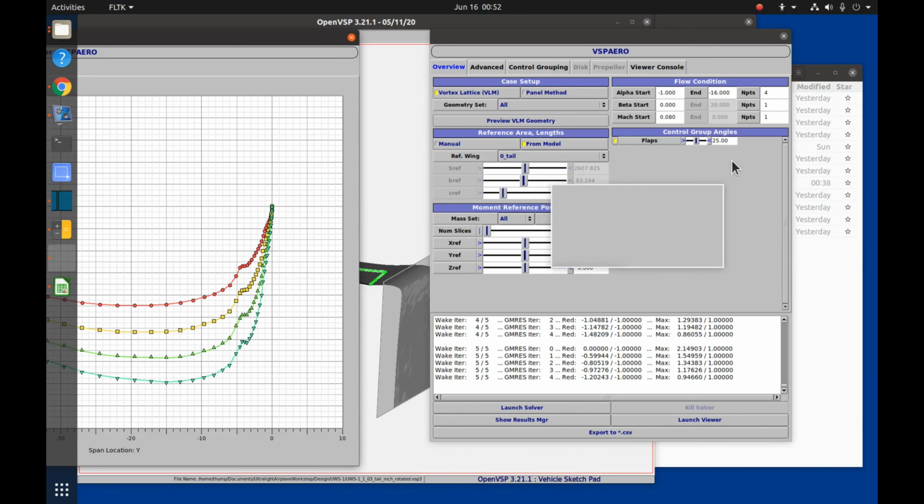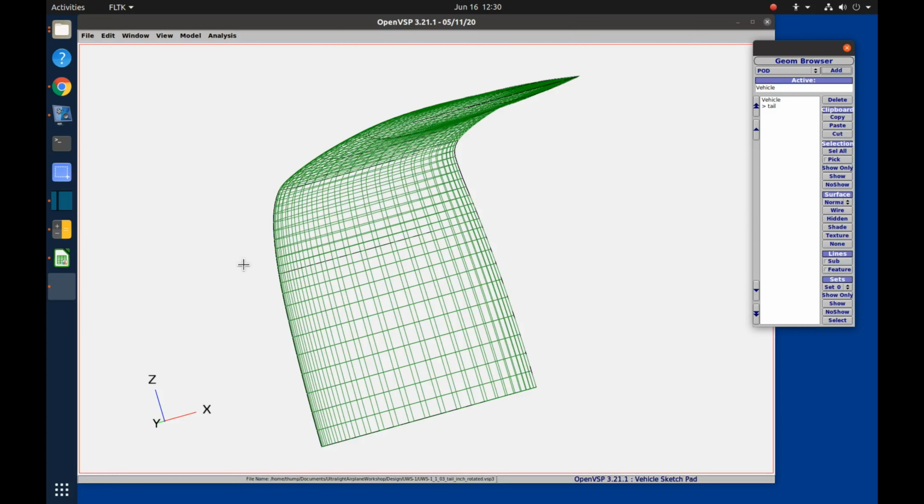So now what we should be doing is getting a lift downward instead of lift upward like we did before, given the current orientation that we have of our vertical tail. And again, let's take a quick look at a picture to understand this pitch and rudder movement. We're now pitching down the vertical stabilizer. The relative wind is still coming in straight and horizontal, and the rudder in this case is flipping up.